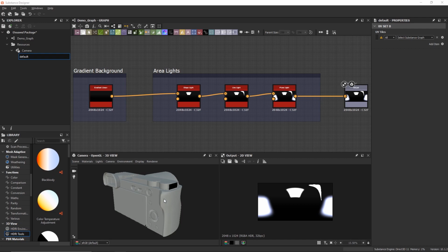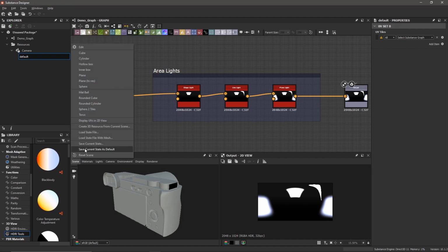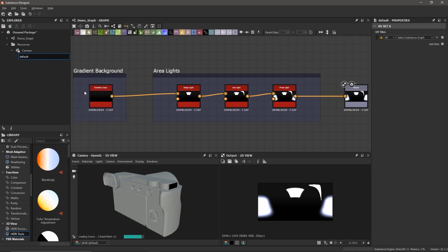While this is a great way to keep everything within Substance Designer, and you can choose to work this way, my particular setup involves me using specific materials and Redshift nodes, such as the awesome round corners node. So I'll stick with the material ball because everyone has it, and it shows a good enough approximation for me. So I'm going to go to Scene, and then choose Matte Ball.